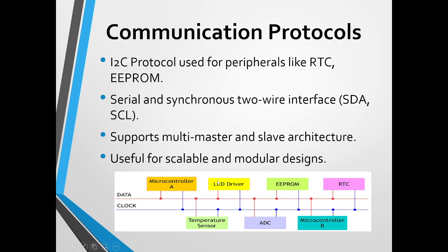So what are communication protocols? The I2C communication protocol is used for peripherals like RTC, EEPROM. It is a serial and synchronous two-wire interface. It supports the multi-master and slave architecture, and it is useful for scalable and modular designs.